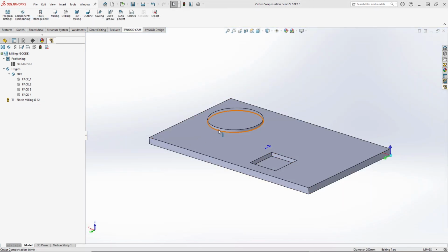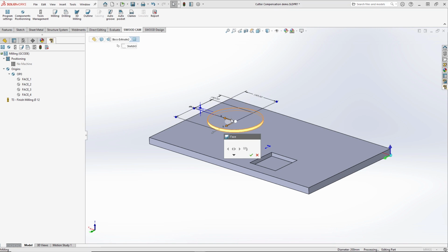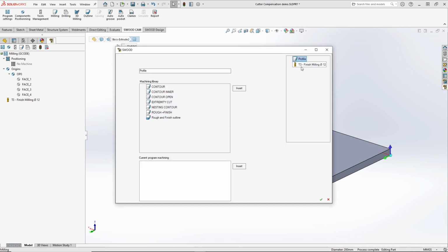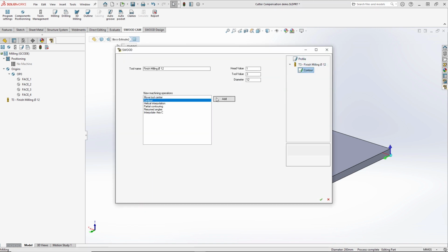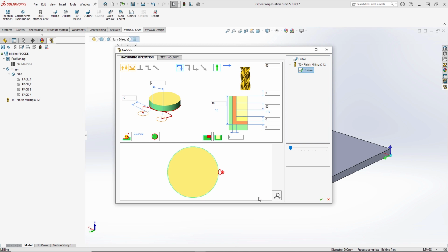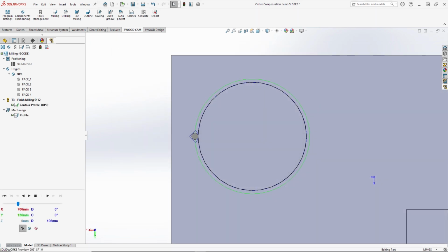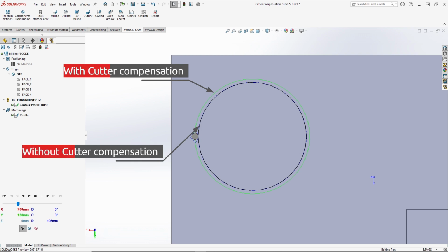This is a similar concept to when applying a contour feature. Cutter compensation is applied by default to a contour operation as it will need to ensure accuracy around the contour face. This is why you will usually see a green toolpath and a blue toolpath in a contour feature. The blue toolpath is the original position with cutter compensation not considered, and then the green toolpath is with cutter compensation, and therefore the distance between those two paths is the cutter compensation's offset.